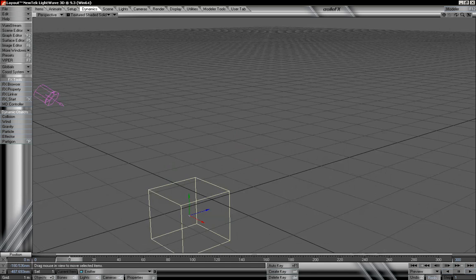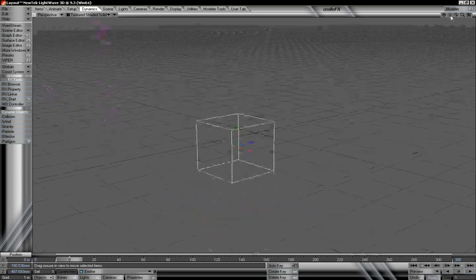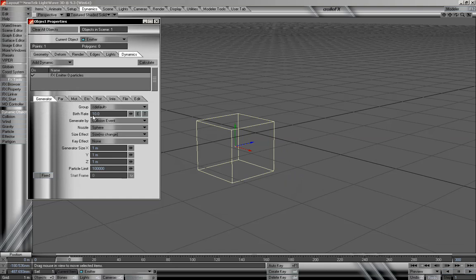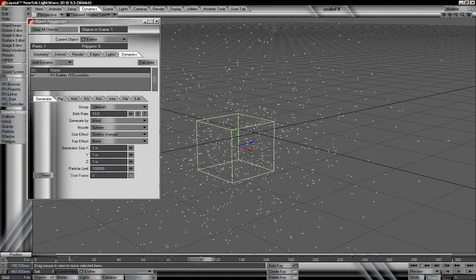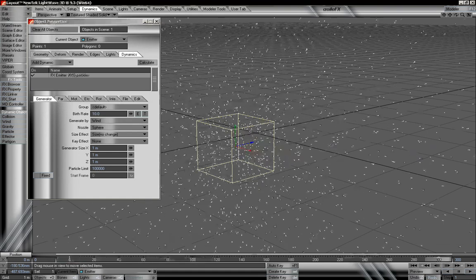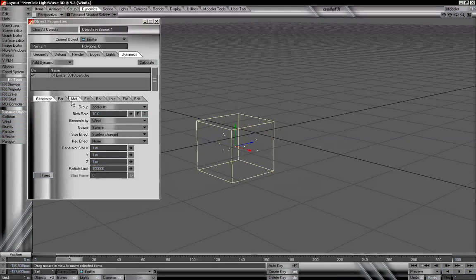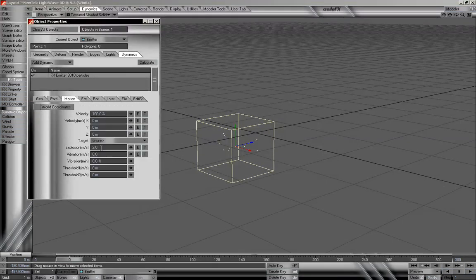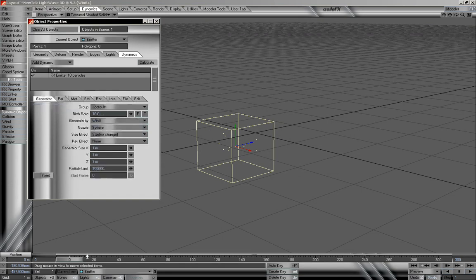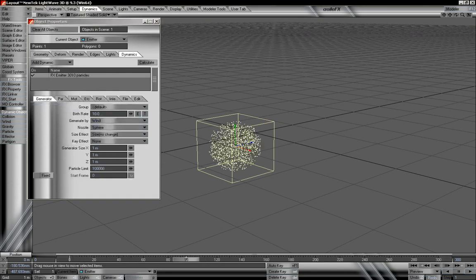and we're going to open up the object properties panel, select our emitter, and we're going to change this to wind. And right now we're not really seeing any major changes. We have the explosion effect on, which we're seeing. Change that down to 0 so that we no longer see that affecting our object.